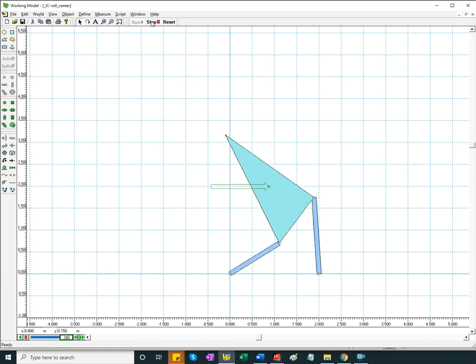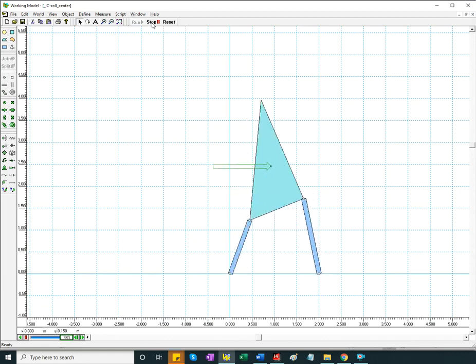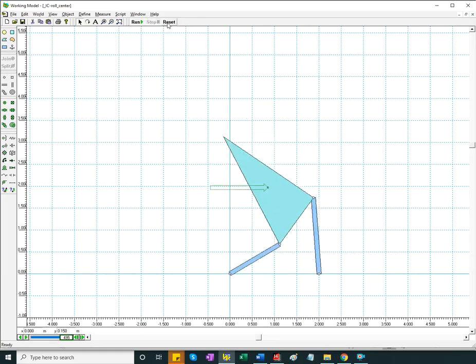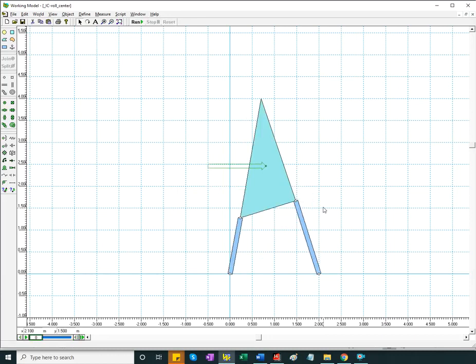Some variations are expected, but if the roll axis and the center of mass are too far apart, this kind of thing can happen: there's a lot of roll of the chassis during a turn. Now, if I move the instant center between the ground and the car body, you can see that very little happens.